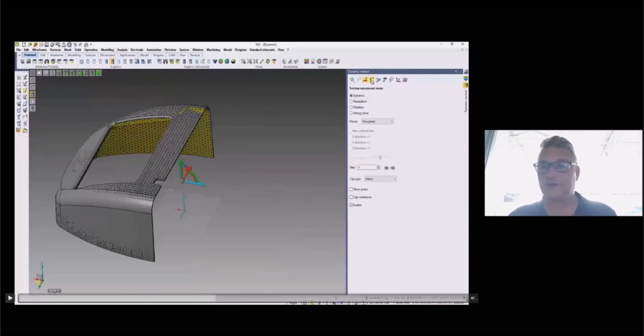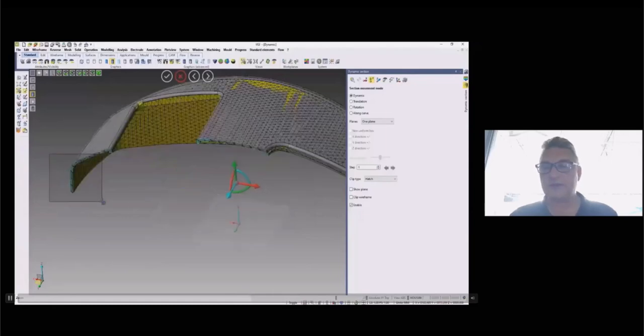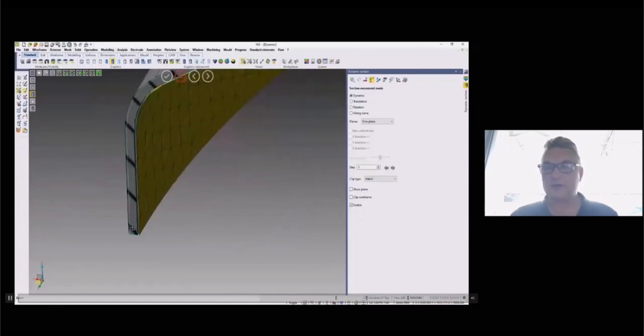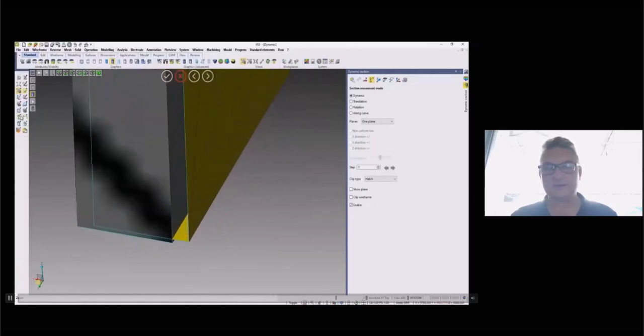Using VISI's fully integrated environment, we can simply select the parts and measure to have a comparison. For example, cutting a dynamic section of both the CAD model and warp model, then create section lines through both parts. Now using the query command, just clicking on 2 points, we have the results of our differences. This is what you can do with a complete all-in-one system.